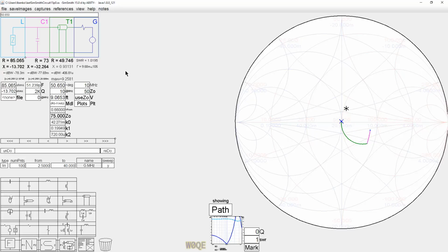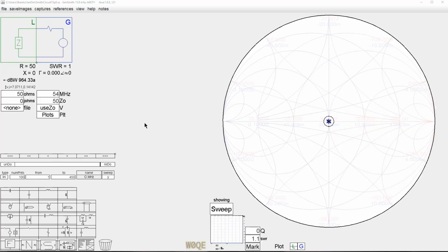Okay, in this case now we've matched it with 50 degrees of transmission line and a 50 picofarad capacitor across the antenna terminals. So there's several ways to match this. Effectively, all of these become basically an L network of some sorts. But it's the kind of thing where, don't get all concerned about the fact that it has to be a magic 90 degrees of rotation. There's plenty of other solutions that are actually better. Now, if you happen to build something that happened to end up being 114 ohms here plus J0, then of course 90 degrees would have been the right solution.